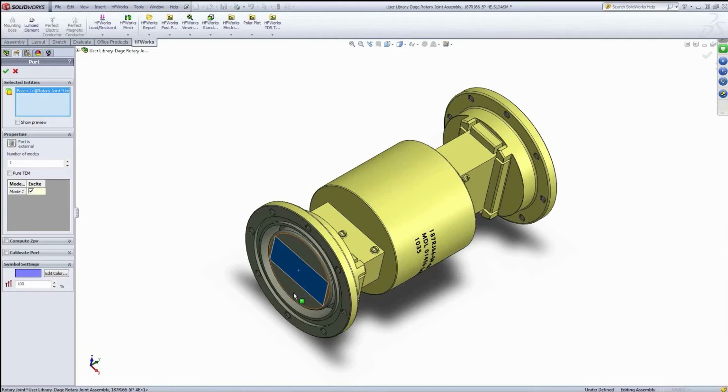That will be the port impedance. If you want to compute it using the voltage definition, then it allows you to define a voltage path where you want to compute the voltage. So we can define a path to say, use the power voltage definition of power, and compute the port impedance that way.